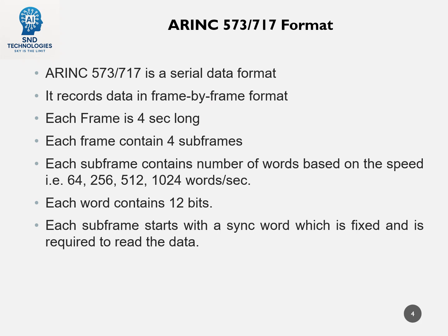So normally in A320 and A330 we have 256 words per second. In 777 also, in the older versions, it was 256 words per second. And in some freighter A330, I've seen 512, and A350 and A380 contain 1024 words per second. Each word consists of 12 bits.